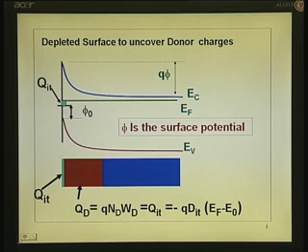Okay, with that I will leave this topic of Fermi level pinning, or the effect of interface state density on the barrier height in a Schottky, and also on the free surface. Please remember that a free surface with high interface state density can lead to a depleted surface below, which has a profound influence on the MOSFET. When we go to that, we will see. Between the gate and the source, there can be a depleted layer due to the free surface. Let me put that down, so that I do not leave you guessing.